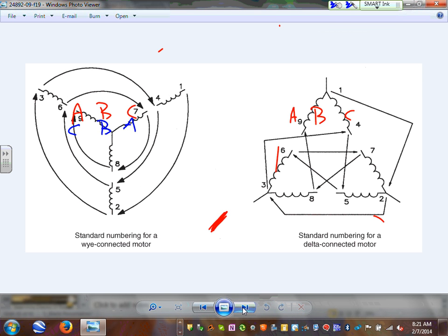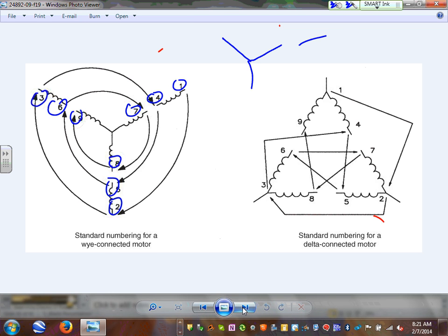The second thing, guys, motors. Three-phase motors in the US come with 9 leads. They call them 9 leads. Derek and everybody else, you guys have done these with us. We have 9 leads. When we do 9 leads, they're labeled, as you guys can see, from here 1, 2, 3, 4, 5, 6, 7, 8, 9. And they always come like this, a 1. Here's how the Y comes. And when you label them, you go clockwise from the top to the bottom, you label them this way.